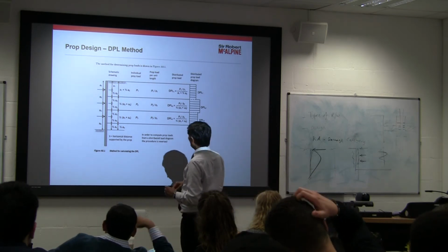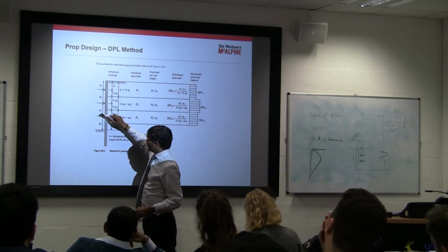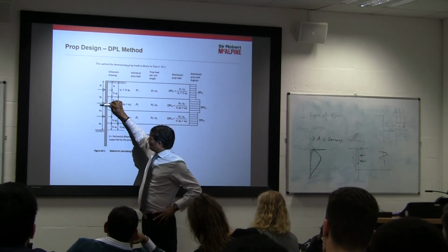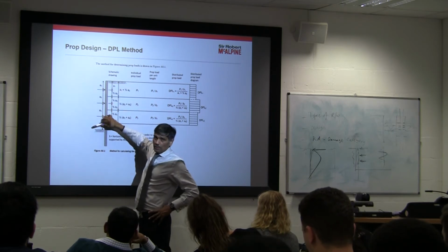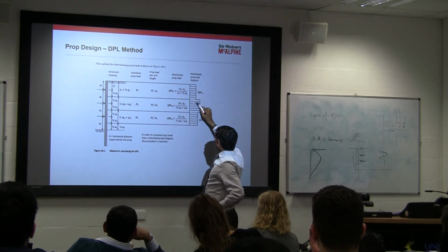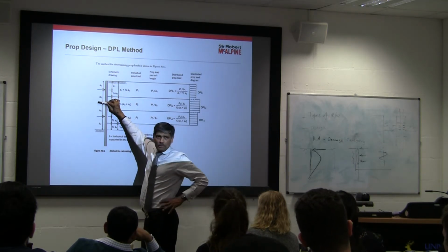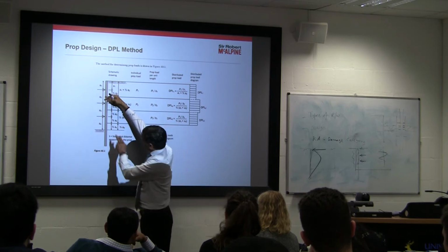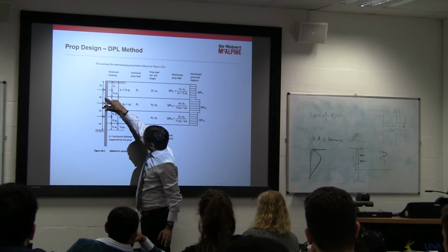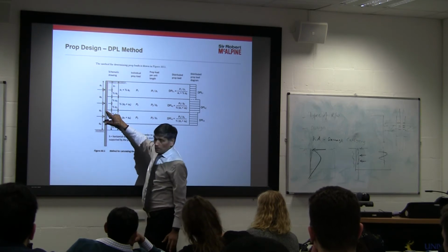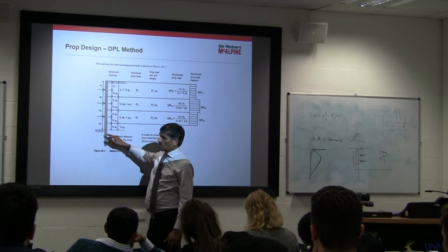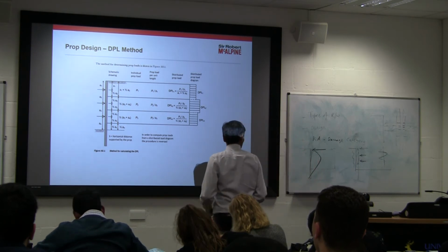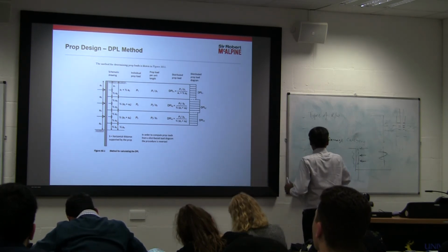So supposing you got multi-level props, you are digging on this side, the pressure is applied on this side. If you got multi-level props, 1, 2, 3 levels, it's a very deep basement. So this tells you the approximate load based on the catchment area of those props, just like any other building column load. How do you work out a column load? Take the catchment area of that prop. Catchment area of that prop is this. Catchment area of that prop is this much. So it's basically a uniformly distributed load method.